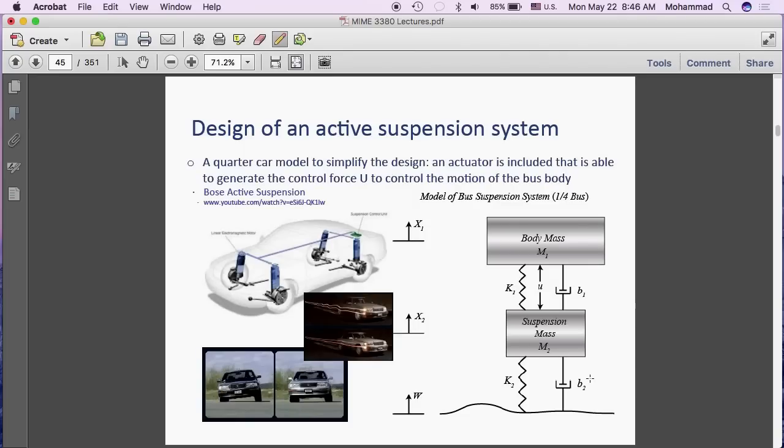If you look closely at this suspension here, these blue objects are not dampers or springs. They're actually linear motors pushing against the wheel, between the wheel and chassis. If the wheel is coming up to push the chassis up, this linear motor would push it down. It will counter it. If on the other side the wheel is going down, you have a pothole, and the chassis will follow, it will push the chassis away to keep it horizontal. So that's the simple way of describing it.